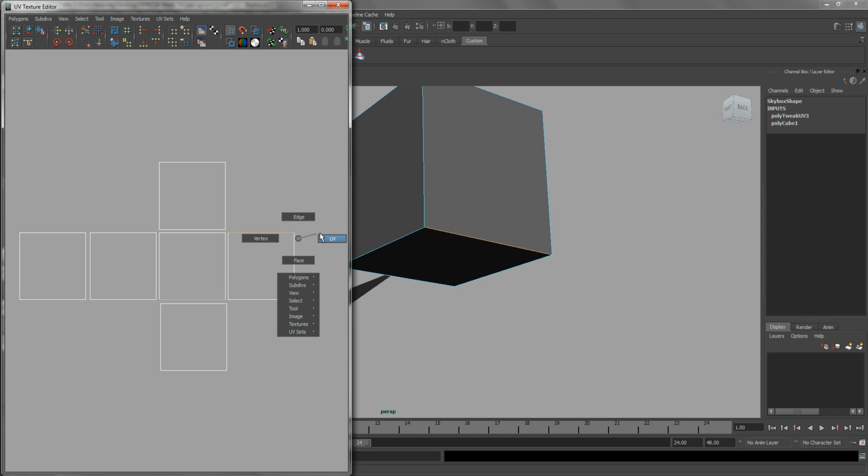So in this case, go to UVs, and of course you can move UV shelf too. This will allow us to select the individual UV parts. Alright, so earlier on, this face here, which is my back face UVs, the edge here is upwards, and I need to really face it that way. So I need to rotate it anti-clockwise.